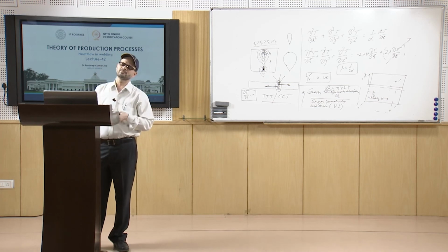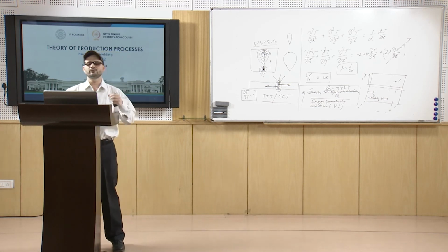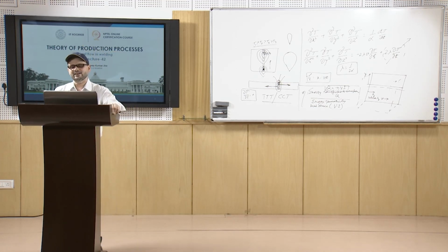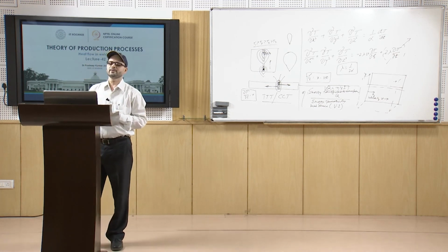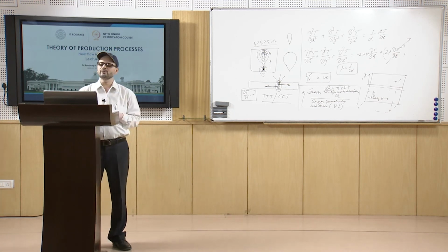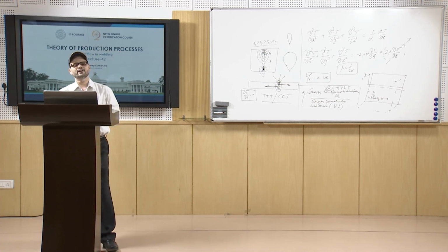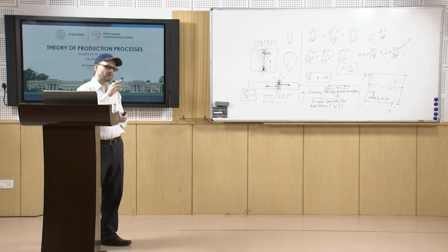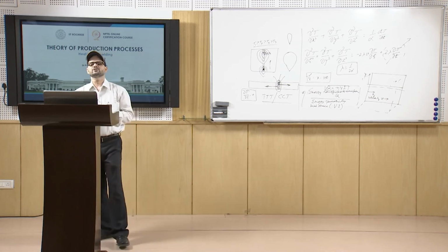So, in a nutshell, if you try to see the efficiency, GTAW varies from 50 to 80 percent for DCEN, and from 20 to 50 percent for normal AC. Similarly, gas metal arc welding will be about 65 to 85 percent. Submerged arc welding goes from 80 to 99 percent, quite higher among the arc welding processes.